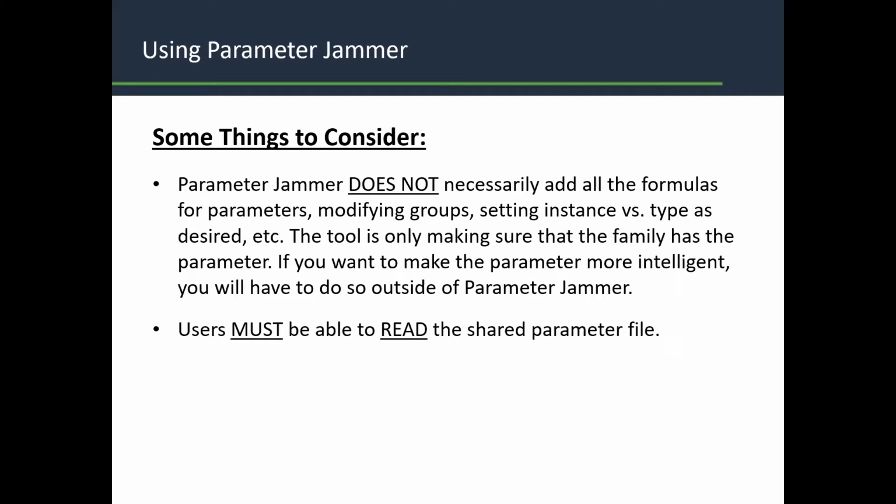And then for the BIM managers and the companies, you guys need to make sure that your users are able to read the shared parameter file. They don't necessarily need to be able to write to it or make changes to it, but they need to have access to it, and their machine needs to be able to read it in order for it to work with the BIM.